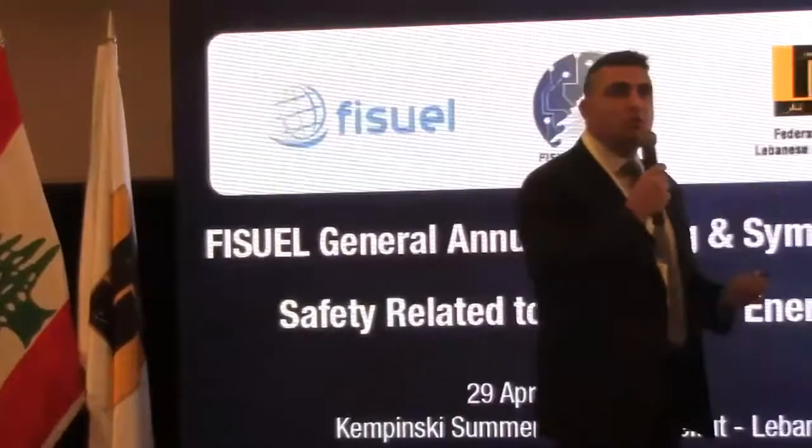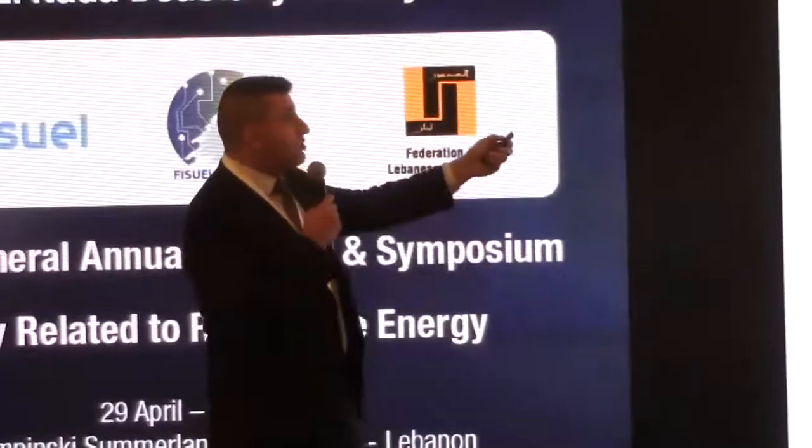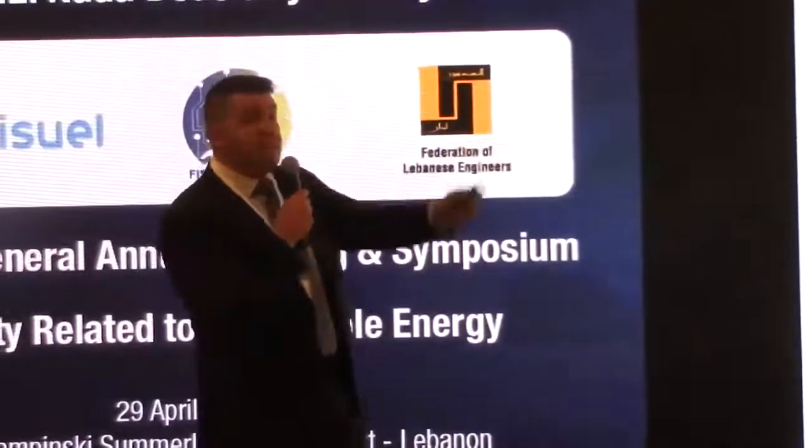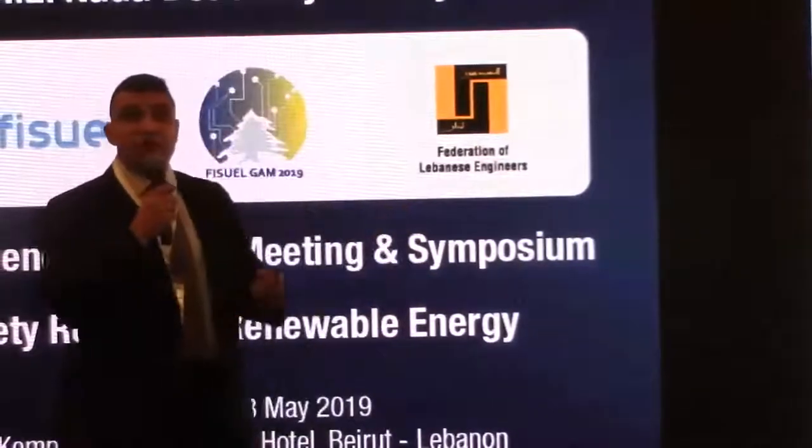Now, after we obtain all this information, we need to decide as an engineer on the layout and product. So it's very critical for us to know the soil resistivity, the ground flash density, the insulation level. The reason is, based on this information, we will make a decision. Do we place the mast touching the structure or not?